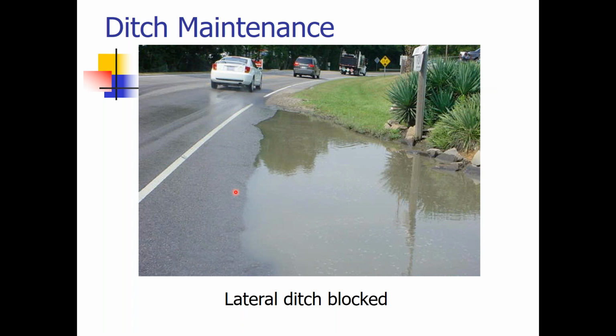Sometimes it's debris that needs to be taken out, but we need to make sure that we're on a regular schedule, checking our ditches and making sure they are free of debris. They are not being blocked. We've talked about lateral ditches, and the idea is keep the water away, okay, from the roadway. It runs lateral to the roadway, but it keeps water away.